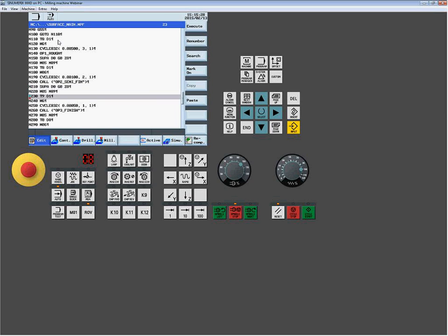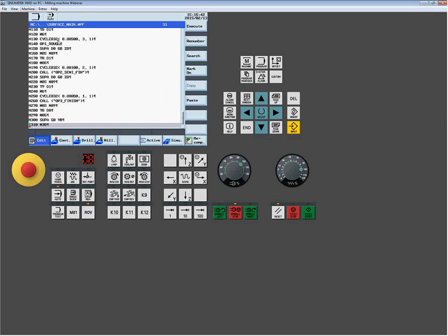So we load it up. Down here at the bottom, I'm doing my normal shutdown. Shut off my spindle, shut off my coolant. I'm cleaning my tool, so I'm clearing my spindle. I'm disabling my tool offset. I do a quick change to actually clear the spindle. I use the super command again to stage my table at a safe point for loading, and I shut off my program.